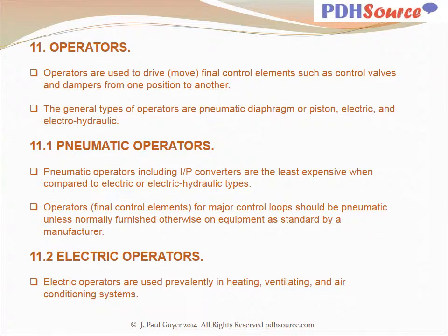Operators are used to drive final control elements such as control valves and dampers from one position to another. The general types of operators are pneumatic diaphragm or piston, electric, and electro-hydraulic. Pneumatic operators, including IP converters, are the least expensive when compared to electric or electro-hydraulic types.